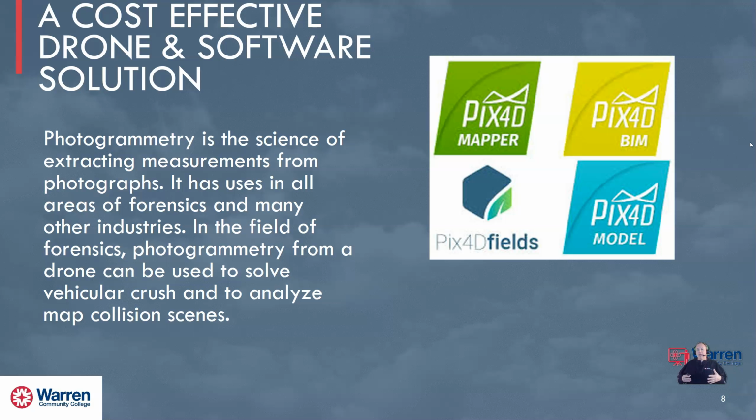So what you need to understand is, if we take the picture on the screen of me, you can't, from a single image, tell my height, you can't tell how many inches. But if you were to capture multiple images of me from multiple varied points around me, oblique around me, nadir above me, and then link these together by their pixels, you could create a scalable image, and this is what we call an orthomosaic image. You could put all these pictures together and then actually measure my height, and that's what we're talking about when we talk about measurement.